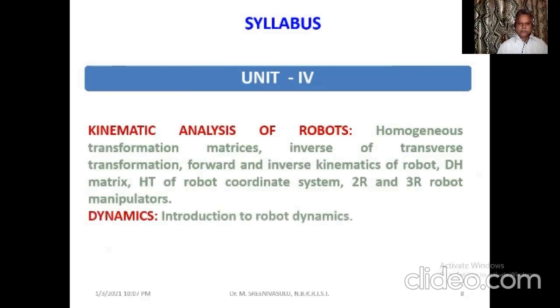wherein, say, when you want to achieve a sort of movement, maybe with the support of joint space or with the support of Cartesian space, both the schemes are very, very important, because when you are trying to move the robot, you are going to give instructions to the joint motors, and you need to attain smooth and continuous motion. For the sake of that, the instruction is going to be given to run the motors in a systematic manner.